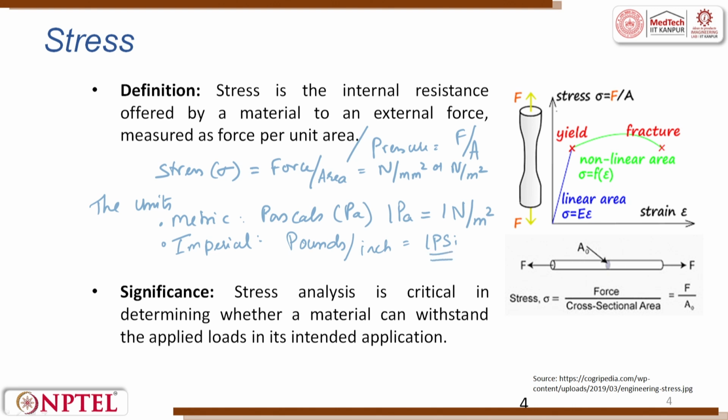If you see here, generally when the material is tested, it will be plotted as stress versus strain. So, this becomes stress and this becomes strain. Stress is force per unit area, strain we will see is a dimensionless quantity. Here it is tensile, but you can also apply compressive force. The only thing is, it will be plotted in the 4 quadrants.